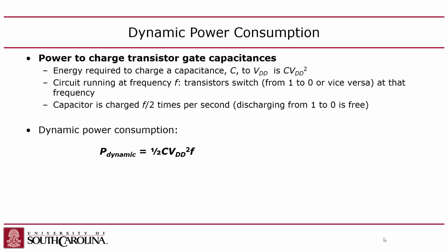The voltage is squared. Now, what controls the capacitance, by the way? Well, the smaller the transistor is, the smaller the plates of the capacitor are, right? So as you shrink the transistors, the capacitance goes down and you become more power efficient. But the problem is if you shrink the transistors, then you end up putting more of them on there, right? So then it makes no difference.